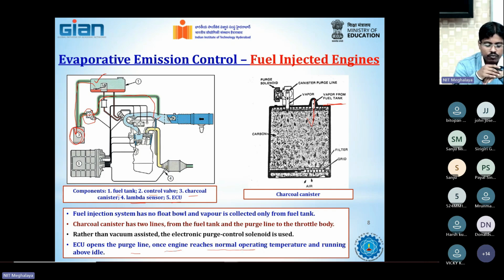It may not be fitted in all the cars, but whenever you are operating a high range car, then definitely you require a canister. Yes, as you told, the charcoal canister is required in petrol engines more specifically, but it is not required in diesel engines, or more specifically, fuel injected engines.